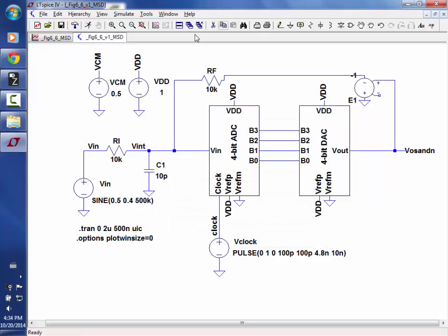And then, of course, if I had 600 millivolts, what is the inverse of that? 400, because it's going to invert around the common mode. Does anybody not understand that? So 800 would invert to 200. So I can't use this circuit without putting the common mode voltage there.